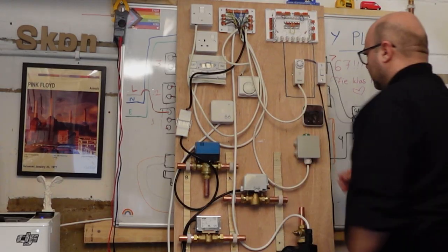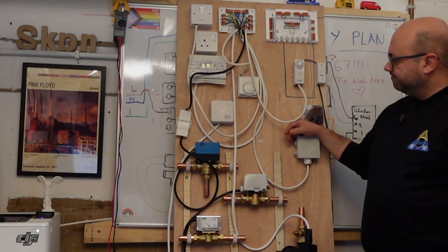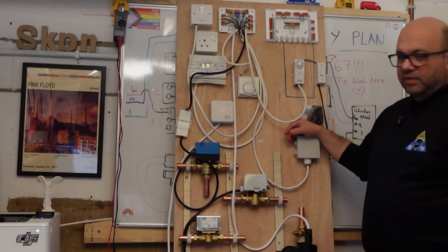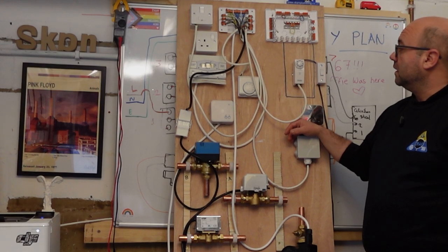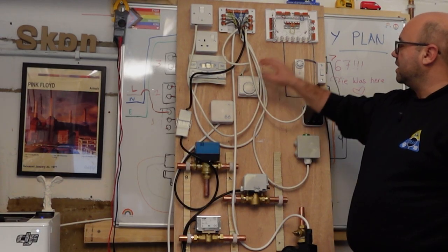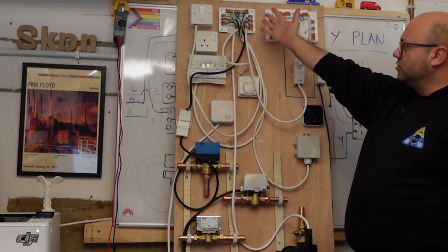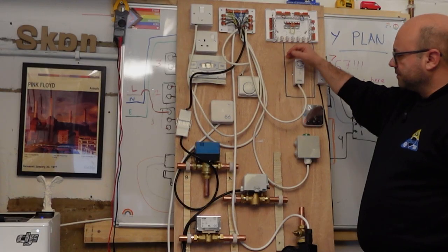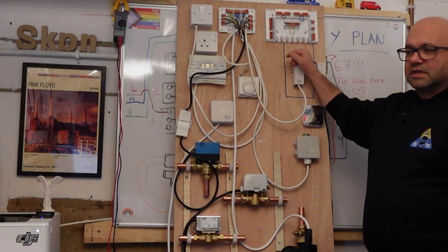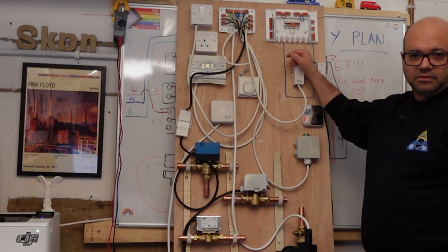Today we're gonna speak about the fault finding methodology. I would like to concentrate today on the three-port valve methodology. When we have the classic configuration with a timer, Drayton timer, Honeywell thermostat, cylinder stat, and Honeywell or WAC box, doesn't really matter, configuration. How many times you've been to the customer and the customer says, Yanis, the heating comes on when the hot water comes on?